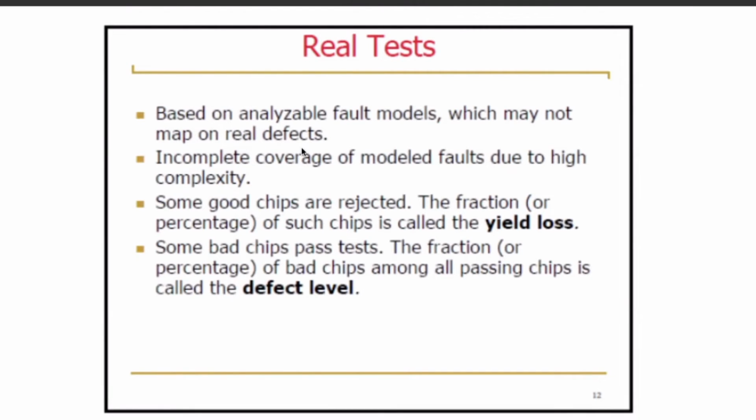We simulate the whole process in ideal testing. But in real testing, we keep some different objectives, and we move around the boundary of these objectives. We have defined the test generation process, we have defined the DFT architecture, we have designed the evaluation matrices, and we have also determined how much confidence we should receive on the evaluations of the test development process.